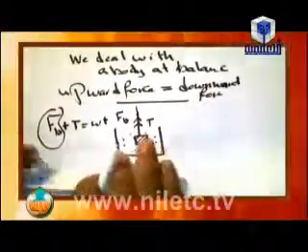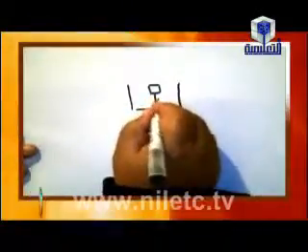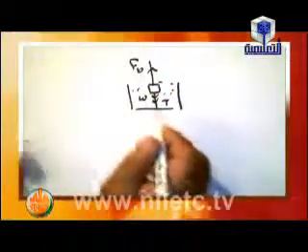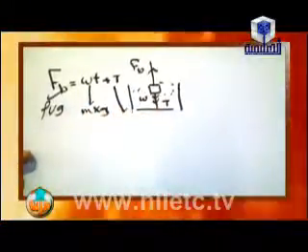If the tension is downward, and the body is pulled downward by tension T and the weight W, and FB upward, we find that the upward force is equal to the downward force. FB equals weight plus tension. We can find FB, which is equal to rho V g. Weight equals m times g, and we can find the tension in the wire.